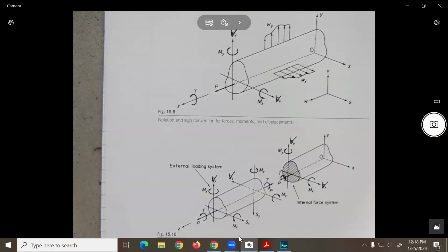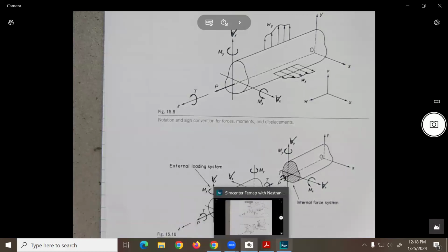Really, in structures, we should be talking about tension for positive and compression for negative, no? I think it's a lot easier to find the sign when you look at the structure and use common sense, is this member in tension or in compression, than having to trust the equations. But the equations are complicated enough here that you can lose sight of what is really happening physically.